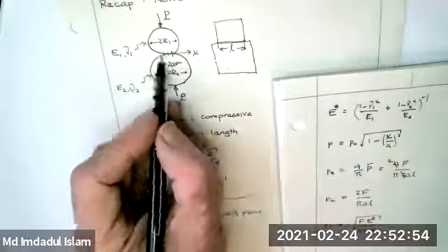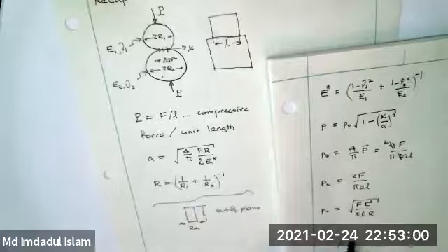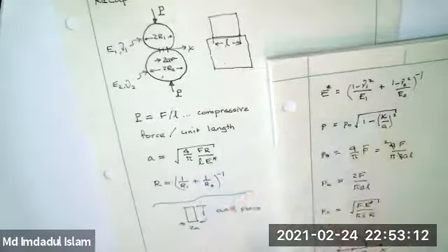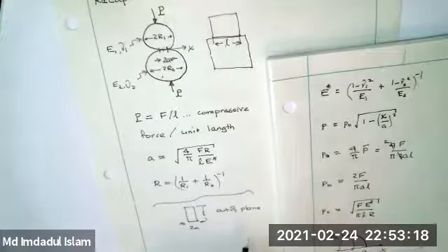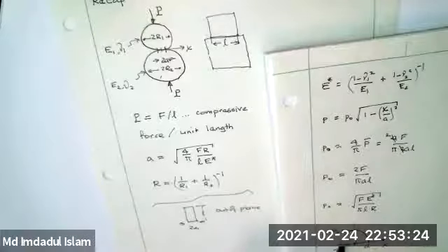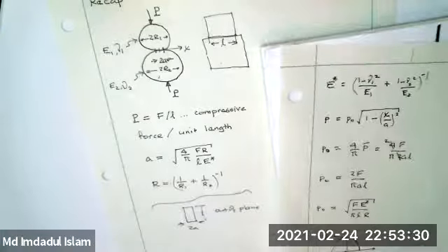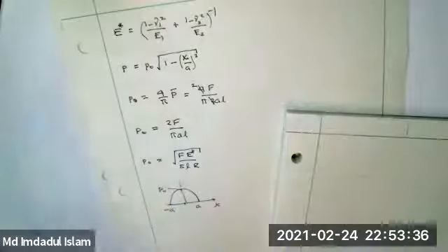And so as you go across the contact region, the stress looks like this. When you get to the edges, X equals A, this will be 0. It has a peak value here in the middle of P naught, okay? That's true of nearly all contact problems. They go down like the square root at the edges. So this stuff's a little counterintuitive compared to what you've had until you live with it for a while.